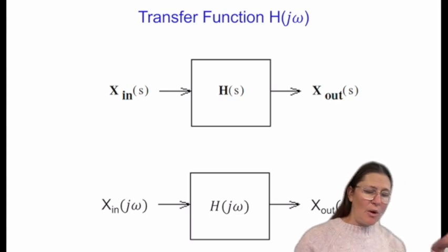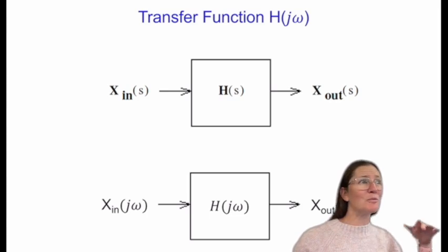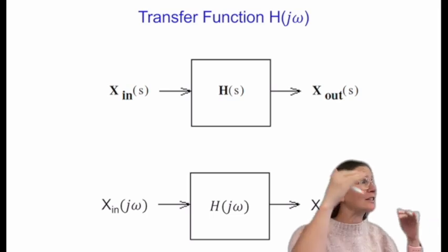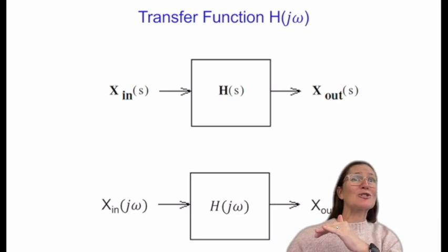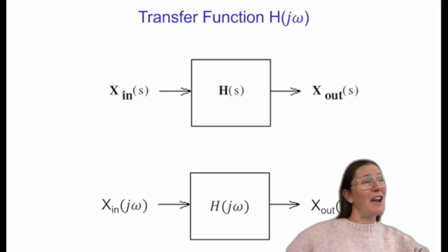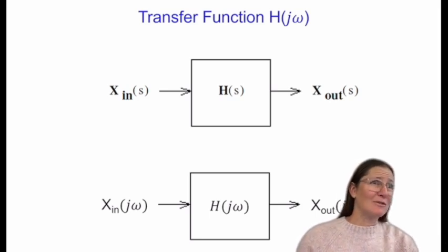As I mentioned earlier, it's hard to use the derivative itself, like the dV/dt, for every capacitor in my circuit. If I have 5 of them, I'm going to get a 5th order differential equation that is going to be a nightmare to solve.